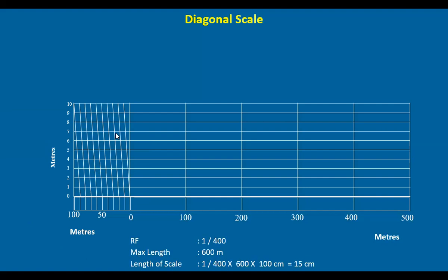Now we can measure whatever length can be given. So show 438 meters. Now let's take 400 meters here. Draw a line and 38: 3 times 10, this is 10, 20, 30 meters. So at this point, you draw, coming to the 8th division on this line.